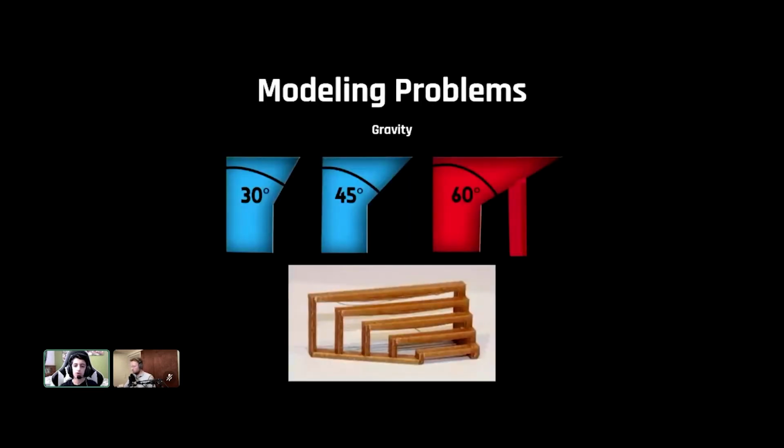When designing 3D models with the intention of 3D printing them, there are a few things to keep in mind. Gravity plays an important role in 3D printing and can cause some problems if the part is not modeled correctly. If the model has more than 45-degree angled parts, the plastic will either start drooping down or just make the print fail altogether. The slicer, which will automatically convert the model into code for the printer, will have to add supports if it has more than 45 degrees.